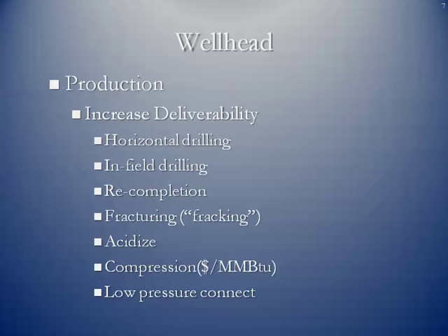Compression. Now, compression is another thing where you can use natural gas compressors to draw additional gas up out of the reservoir once the reservoir pressure itself has dropped to the point where the gas can't just free flow into the connected pipeline. And the other course is to look for what we would call a low pressure connect. This is generally a service that's provided by midstream gatherers and processors, where they have compression at their plant which can draw the gas from your well if the pressure of your well can't by itself exceed the pressure of the pipeline that it's connected to.